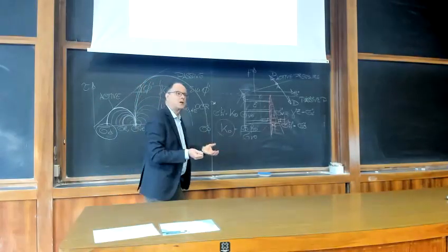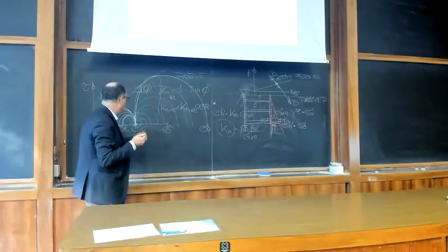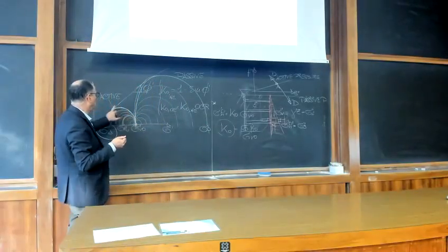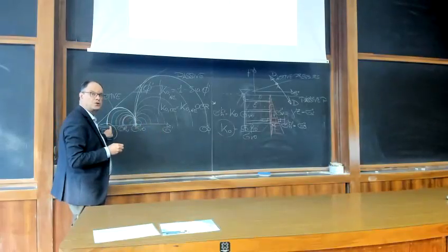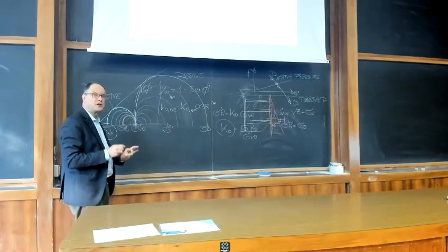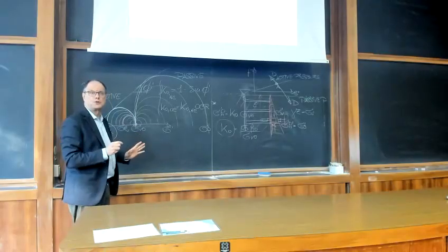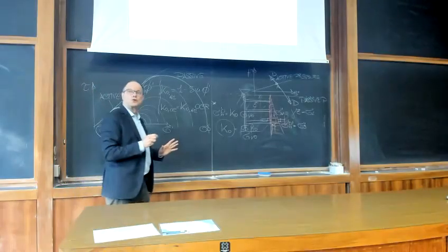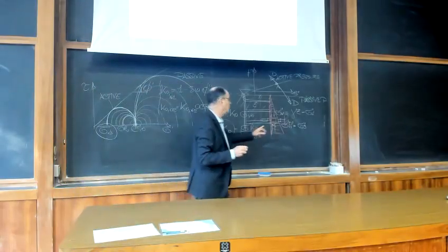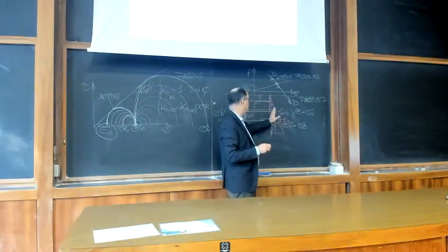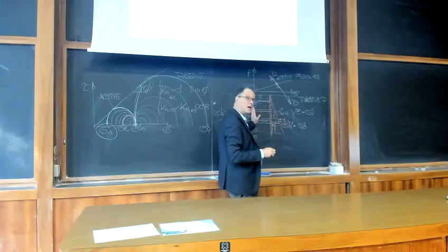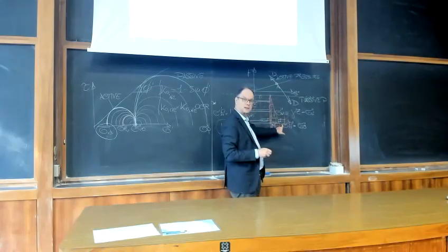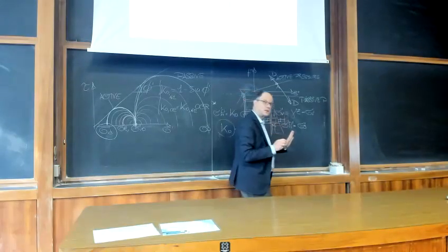Well, behind this assumption, you have to allow your wall to move and expand until it gets to this condition, because the active pressure is the minimum force acting on the wall. So you can design using the minimum force as long as you allow the wall to move sideways enough to get to the active pressure. So never forget this.